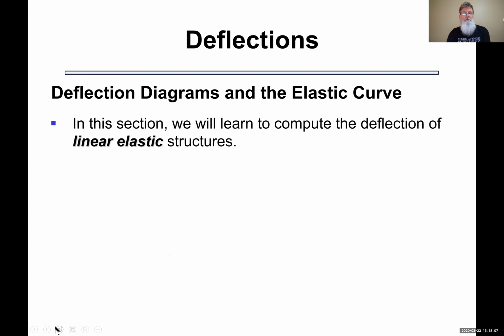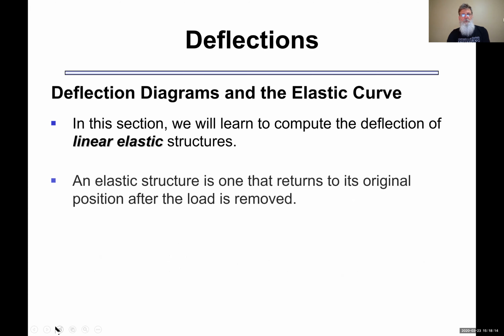So we're going to talk exclusively in our course, since it's an intro course, about linear elastic structures. And you might recall that linear elastic means it follows a linear curve, which would be described by the modulus of elasticity, E, and elastic in that it will return. So when you deform it and unload it, it will return to its original position. If it doesn't, then that's plastic behavior, and that's beyond the scope of our course this time.